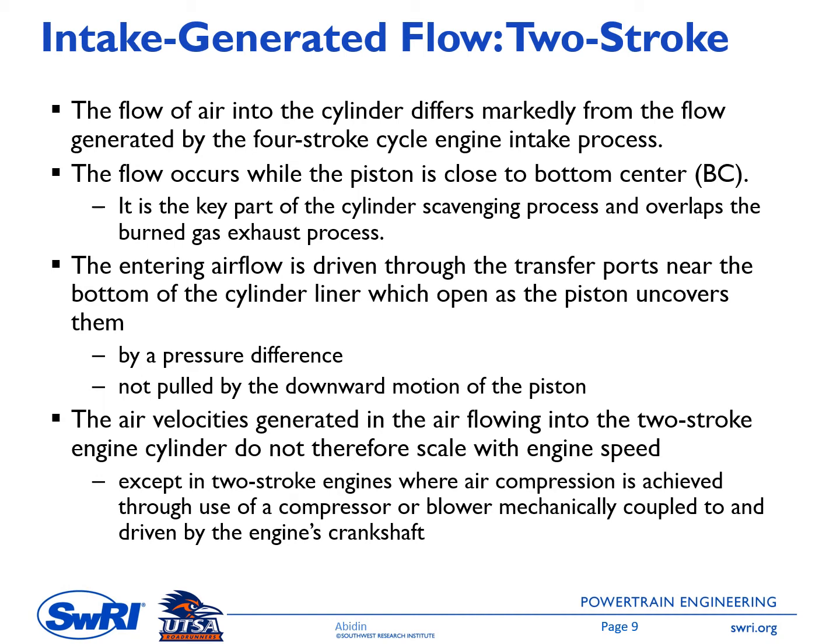So we have the scavenging process, which consists of the exhaust stroke and intake stroke, and they occur simultaneously in a two-stroke engine. The entering airflow is driven through the transfer port near the bottom of the cylinder liner, which opens as the piston uncovers the ports, and this inflow is governed by the pressure difference, okay?